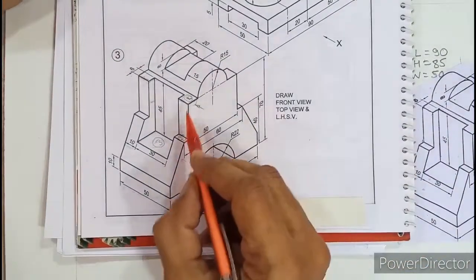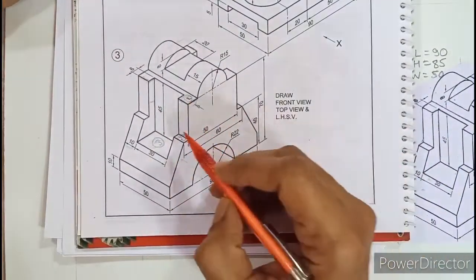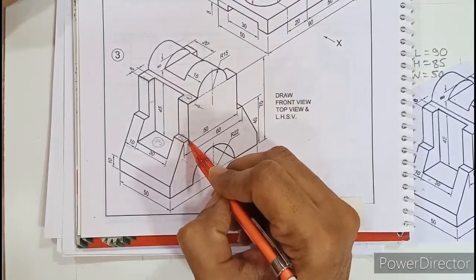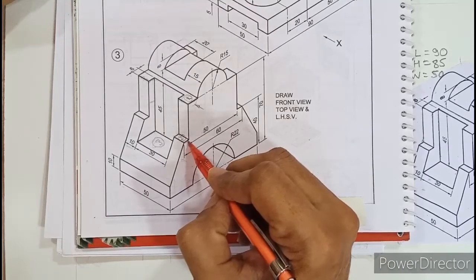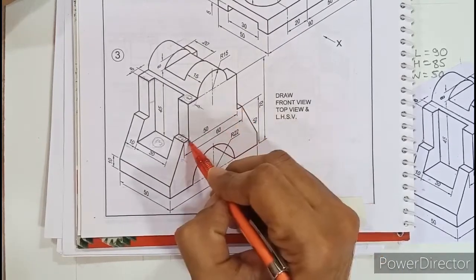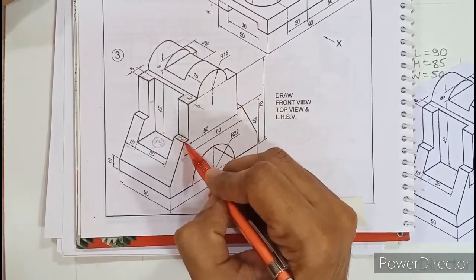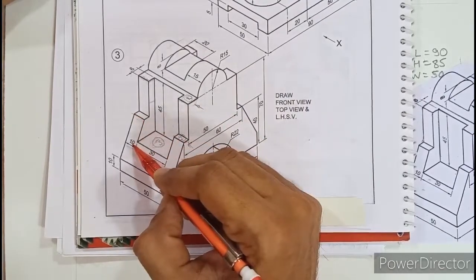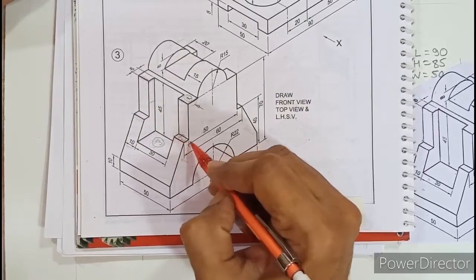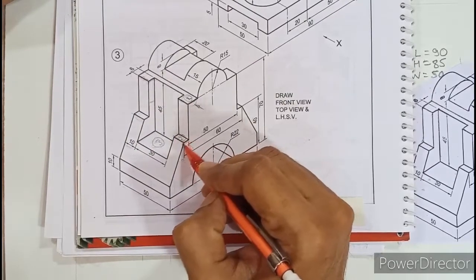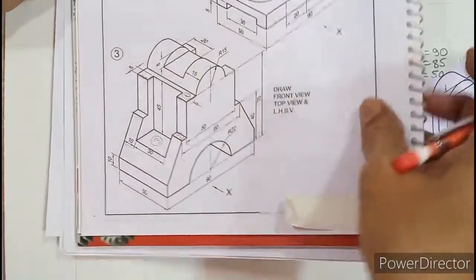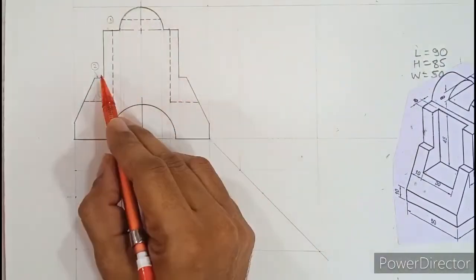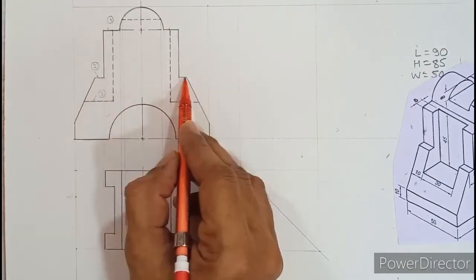So after you're done with this part 1, let us now try to draw the small rectangle 2. For that you need to identify where this small shoulder is coming out in the front view. But the other dimension, that is this width, is the same as this width, and that is 10 millimeter. So the next dimension is 10, but the first dimension you need to recognize from the front view itself. In the front view, this small shoulder coming out is what we already marked 2 over here.